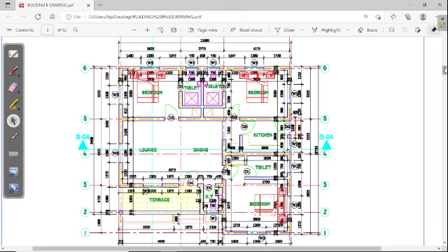If we look at the external dimension of this building, it is a rectangle. Now, to estimate the profile and the pegs and the nails needed for this type of material, certain things must be considered. One of the things that must be considered is the position of the peg away from the building line. Your pegs should not be too close to your building line. If not, by the time you are excavating, the peg may fall off due to caving in of soils. So we usually recommend a distance of 1.5 meters to 2 meters away from the four faces of the building.